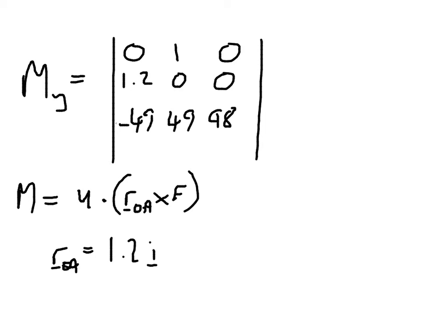That's saying I've got my axis along which I want the thing to turn. I've got my Cartesian vector for my force, so which direction is the force actually acting in, and I've got where it's starting from. So we're saying I've got a force acting in a direction from a starting point. What effect does it have turning it about an axis? I was reading the matrix upwards. Hopefully that makes sense. I'll say that one more time.